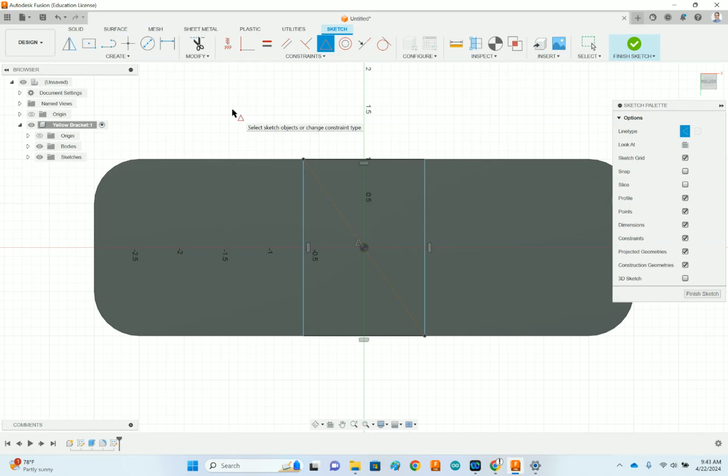So let's go here. Let's turn on the sketch dimension tool. Let's click this line, then move over and click this line, and then move up to the middle. That's a 3-click dimensioning. We do a lot more 3-click dimensioning than 2-click dimensioning. The last click is always where you drop your dimension so that when somebody looks at it, they can find that number. So I clicked here, then I clicked here, then I moved up to here so I could see the number. It wouldn't get hidden by the part. And I click a third time there.